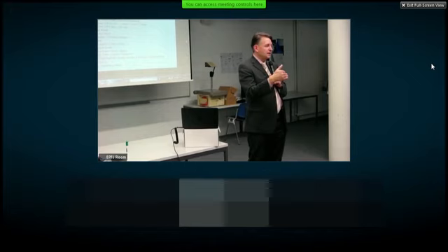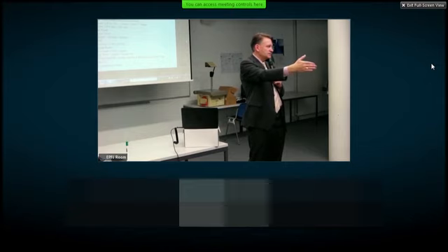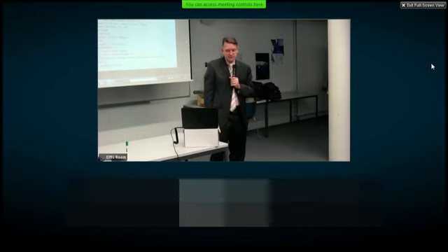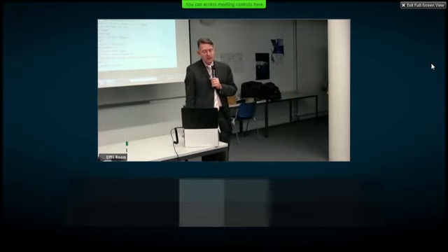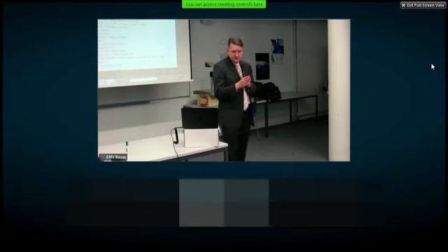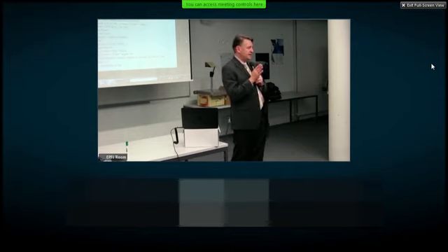The problem with DC power is there are huge losses with distance. And with AC, you can go to very high voltages and transmit power with relatively little loss over large distance. That's the main reason that AC won out, essentially. The thing that's important here, and power, of course, is current times voltage. The thing that's important is that these voltage levels, and in the case of AC power, also the frequency is very important, 50 or 60 hertz. This is very standardized, okay?